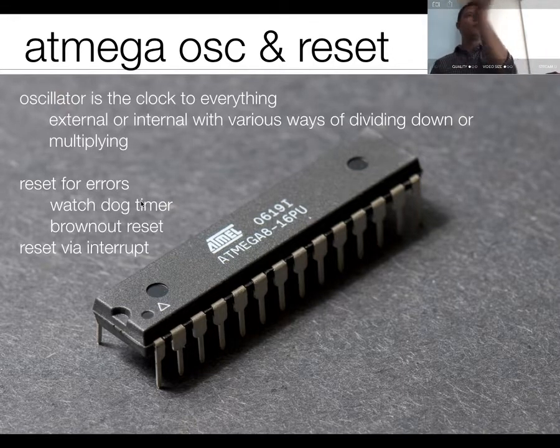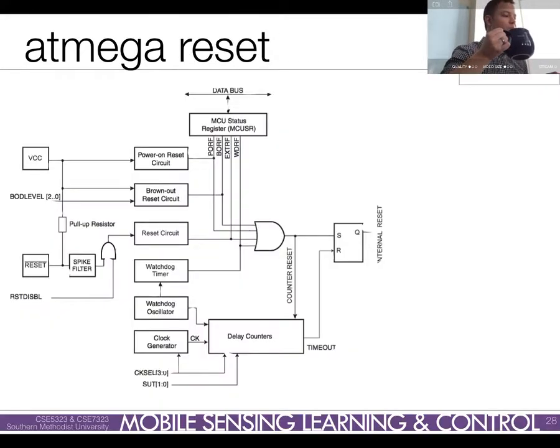And you would be doing stuff in your microcontroller, you'd reset the Watchdog Timer. So if ever you got into a place where you weren't supposed to be, the Watchdog Timer would just sit there and it would overflow, reset the chip, and essentially try and communicate back down to earth. All right? That's where the Watchdog Timer essentially came from. It's now used on every single microcontroller. And it's the bane of your existence. Okay? But you can disable it.